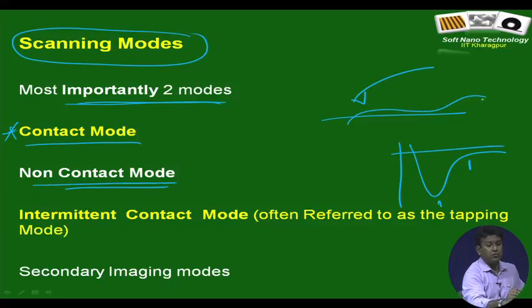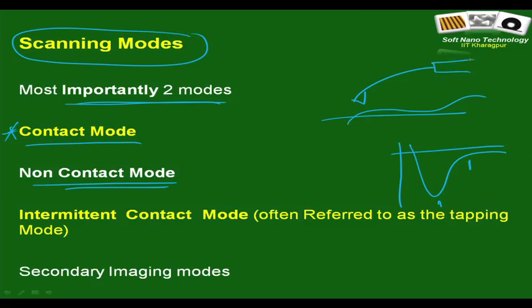Now, as the cantilever moves, as the surface goes further away or becomes closer to the cantilever, it can still change the deflection. It is scientifically very sound, robust, and very exciting also, because it does not touch the surface. It is really relying on the interaction forces, because if you look at the approach sequence of the contact mode cantilever, you are not exactly relying on van der Waals force anymore, you are actually relying on brute force repulsion. But non-contact mode imaging in principle relies completely on van der Waals forces, but in reality the resolution is